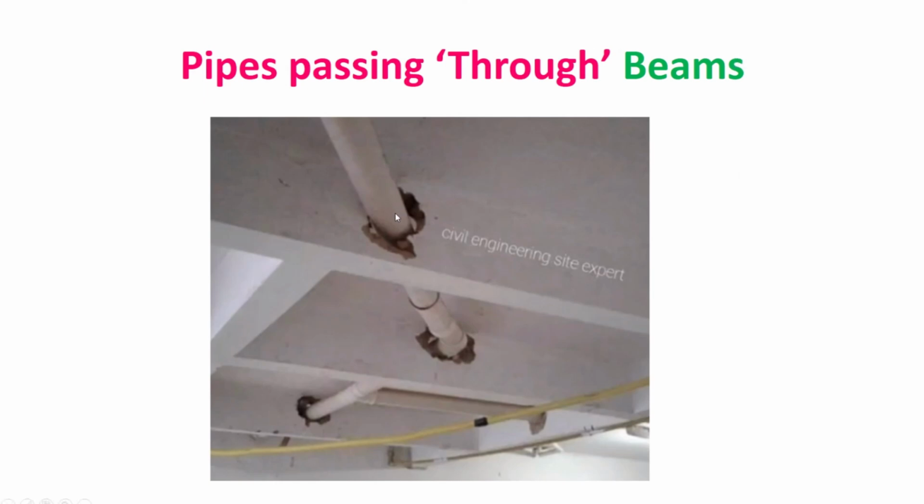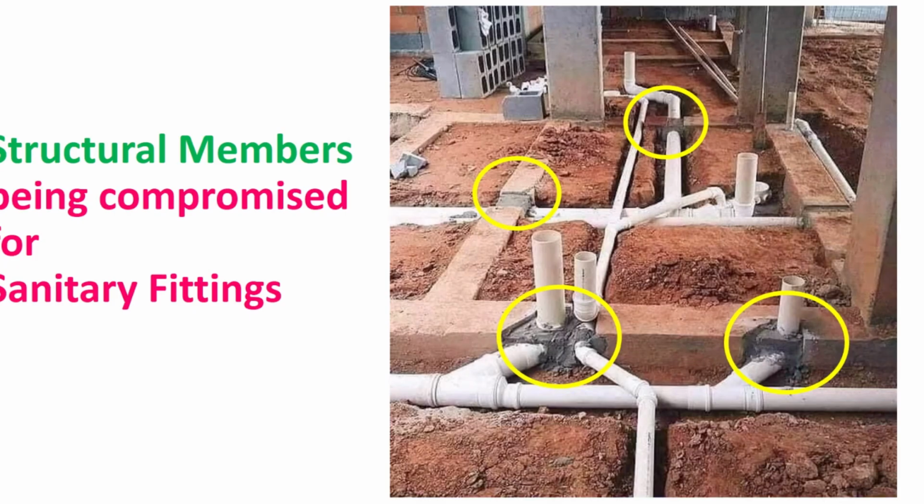Yes. So you must be aware, whenever you have learned about your academics also, when water is in that particular range, there is something called saturation of that water, or it will be in a submerged condition. So in submerged condition, there is an uplift force and your net weight will be reduced. In that case, as you must have seen, normally it reduces by 50%. So you have to redesign that.